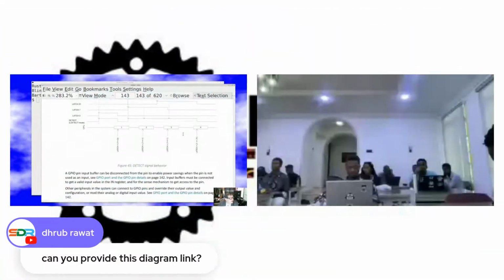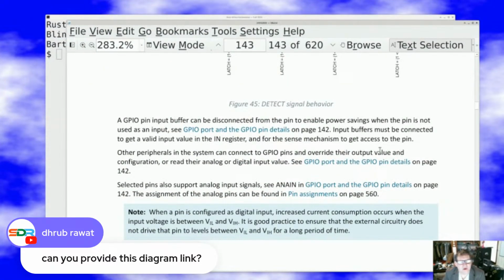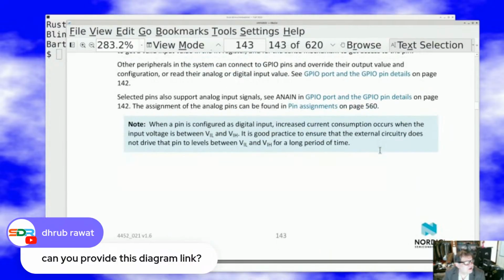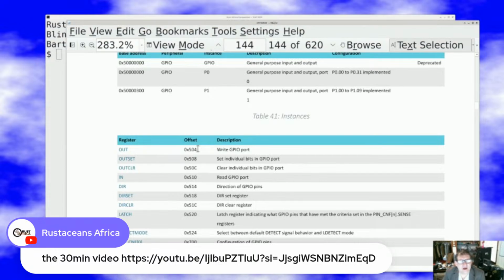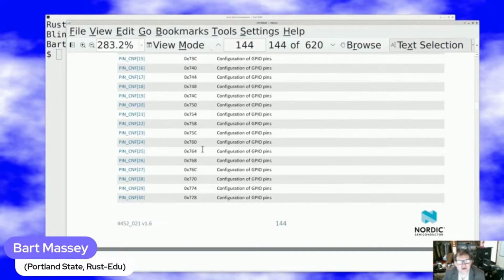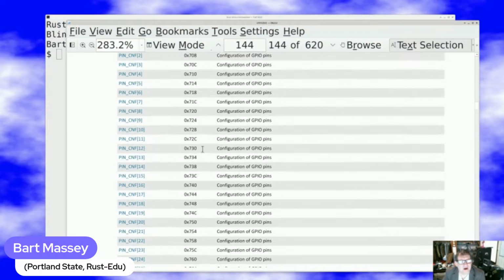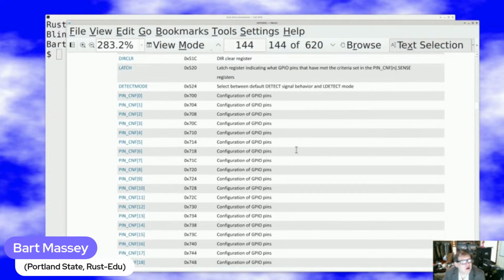And so there's a lot of detail about how this works that today I'm going to ignore. It's in that supplementary video I mentioned where we go into a lot of detail about all the registers and stuff. But very briefly, the important idea here is that there are these locations that look like they're in program memory, but when you store into them or read from them, it doesn't actually put stuff in memory. Instead, it makes the microcontroller's hardware do things. And so there's a whole bunch of memory locations described in this manual that allow you to change what's going on with the GPIO pins. So by manipulating the device registers in the computer, which are just memory locations, you can make the pin be an output pin, with the voltage we want. So that's what we're going to do. That's what's going on at the lower level.